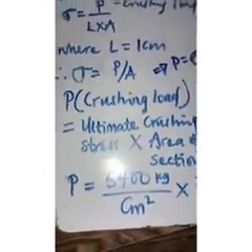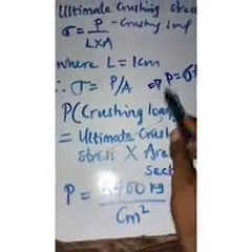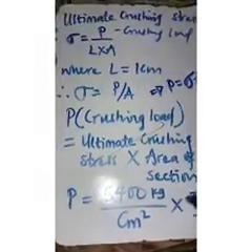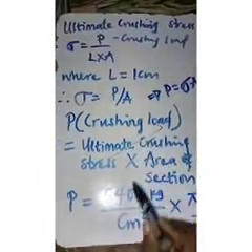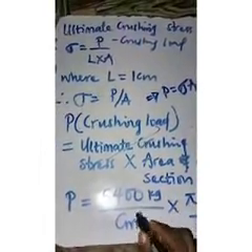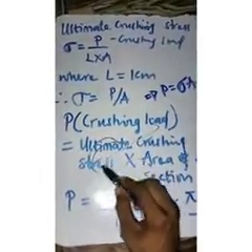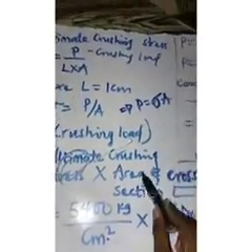So if I cross multiply, I can have my ultimate crushing stress here. If you remember the formula we derived, I will have it as this times the area, and I can have it as 5,400 kilogram per centimeter square. If you remember from the question, the parameter we are given is in kilogram per centimeter square, and the area of the cross section is now derived as this.